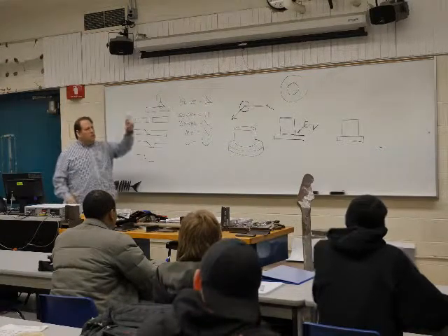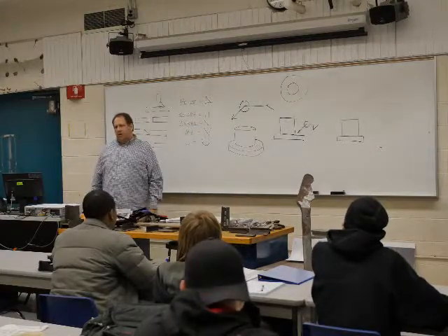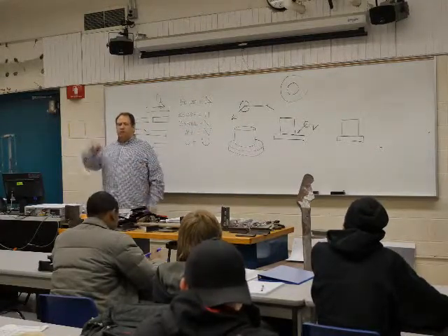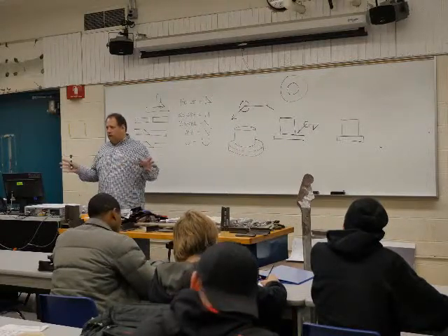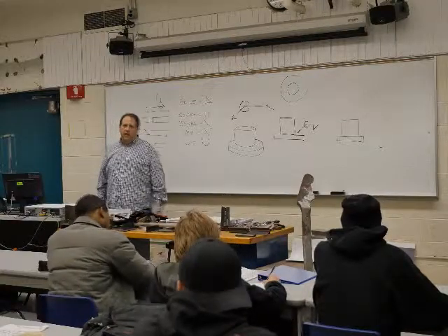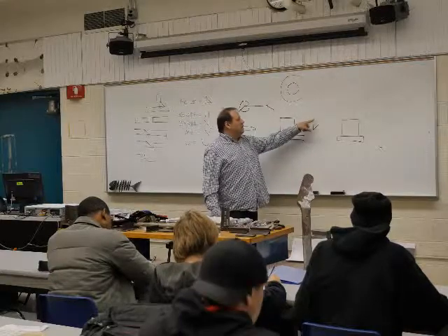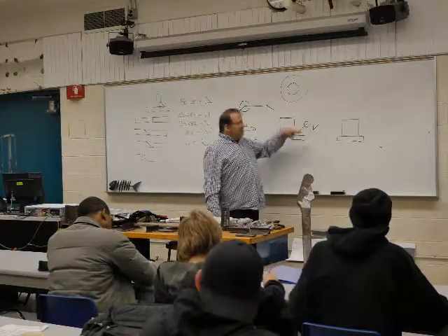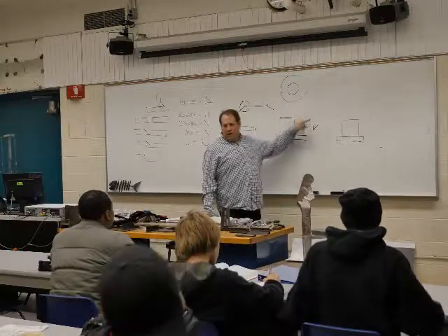No, because the weld all around symbol trumps what side that goes on. It's natural to just put it on the top. If you're doing it on the computer, or drawing it out physically, it's just easier to draw that fillet weld symbol on top of the line. But this trumps where it is, this side or this side. This is already telling us we have to weld all the way around it. It doesn't really matter. It really didn't change anything.